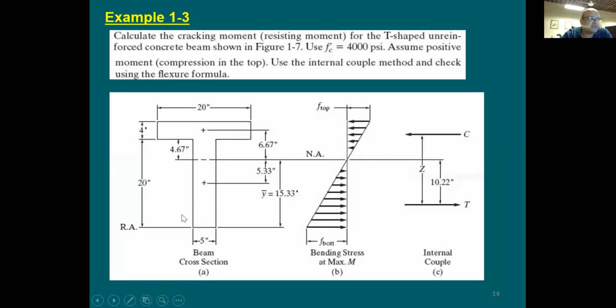And the moment arm to this axis is going to be equal to 24 minus 2, correct? Why? Because this area is going to be concentrated right here in the top flange at 2 inches from the top. So the distance from this axis, at which we are taking the moment about, to the centroid of section number A1 is going to be equal to 22 inches. Any questions on this? We're good? Good.